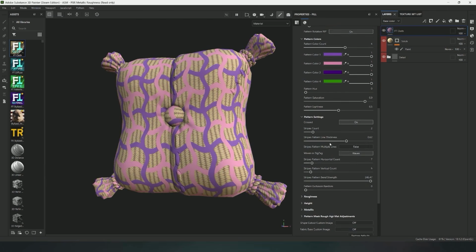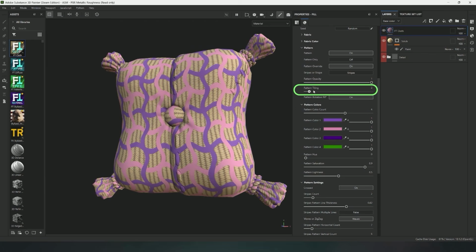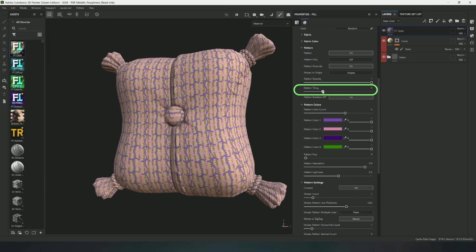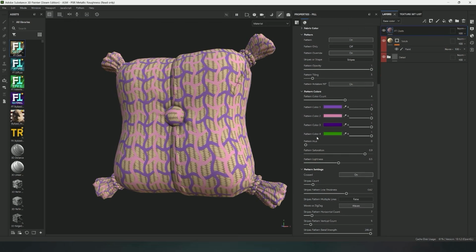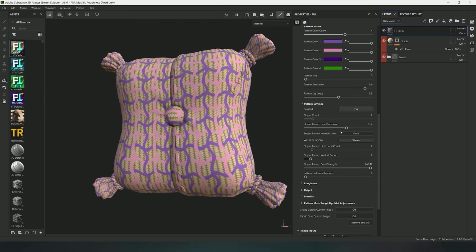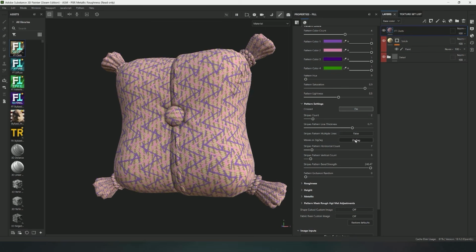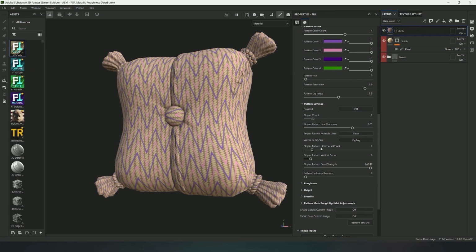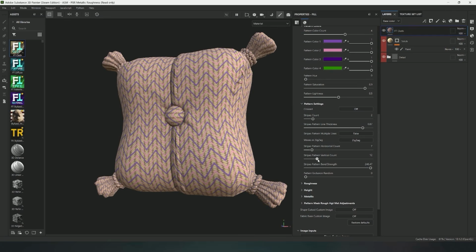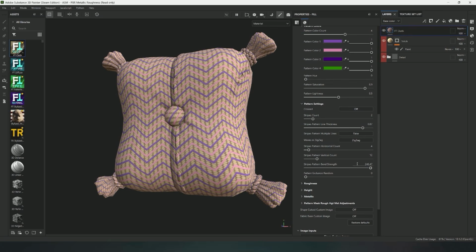To change the pattern scale, just go to the pattern section and increase the tiling. I'll repeat once more, this entire generator is a single unit, and to achieve specific tasks, you need to use all the parameter functionalities. But that's not all, and line settings are just the main function for generating simple patterns that are most often found on fabric. To solve more creative tasks and generate non-standard patterns, there is a shape parameter in the pattern section.